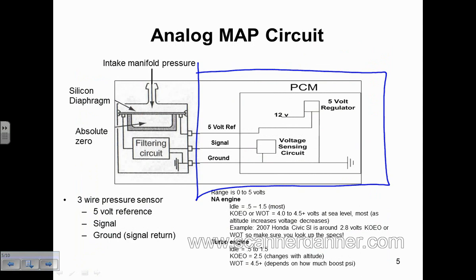You see what the cool part is when we do pressure sensors? When we work on them, we remember all the detail we did: signal fixed high, signal fixed low, it could be this, it could be this. Guess what? It's all the same. And as we continue through this, I'm going to say in here, for detailed testing of the MAP sensor, refer to potentiometers. Some of today's wiring diagrams will actually draw this circuit,